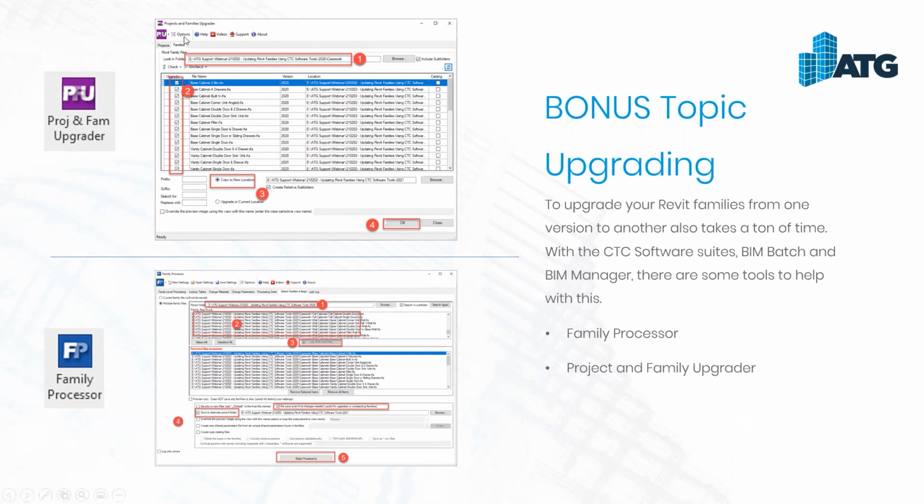Then there's the other tool in the BIM batch suite, Project and Family Upgrader, which allows you to grab the families that you want and upgrade them. It also allows you to pick projects and upgrade those from one version to another. Then there's the option of copy to a new location, which I always recommend for testing purposes to see if it works as you expected, and then run through and do it live if you choose to upgrade in the current place.